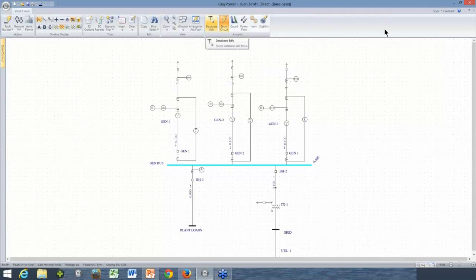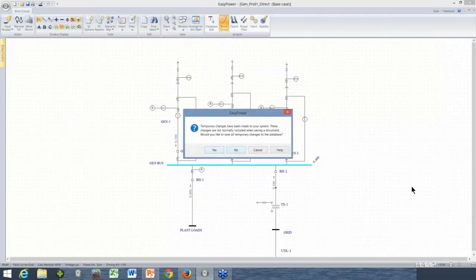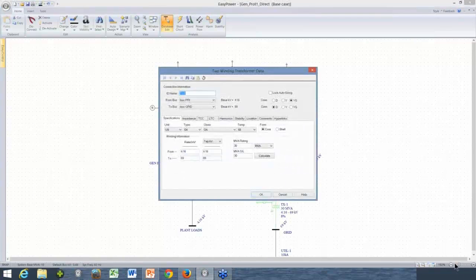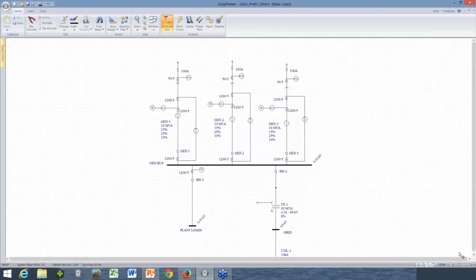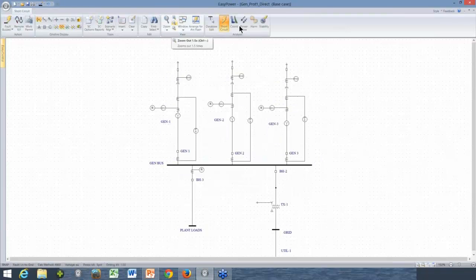All right, so if I go back to the database, let's take a look. If I were to get rid of this grounding resistor and go to solid grounding, so now I have a solidly grounded Y here, and this is a delta. So this is going to be a ground source for my 4160 volt system here. So now when I go back to short circuit, on line to ground, when I do a fault on this bus, now instead of 400 amps, I get 63,000 amps.